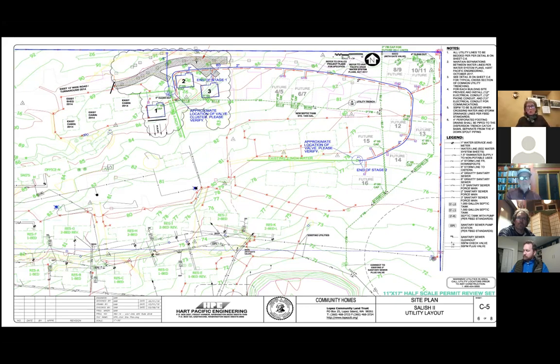And more and more, when you work with contractors, they will tell you, nope, we do not want anything buried on top of another. We like wider ditches, and we like everything side by side, because when we have to go in, nobody wants to be on the bottom, right? Because you have to break through whatever's on the top. And so you just have to get used to doing that.